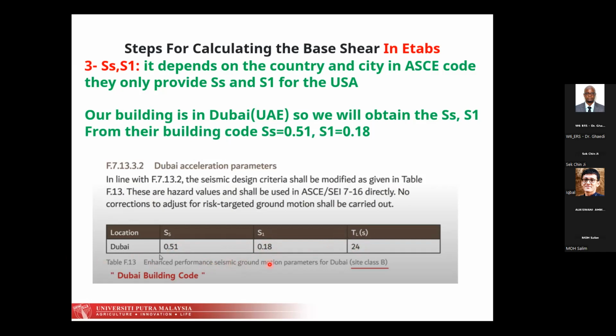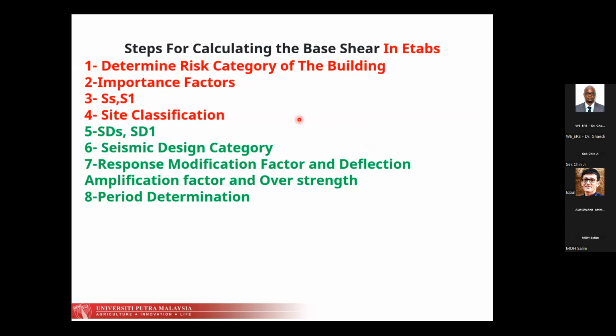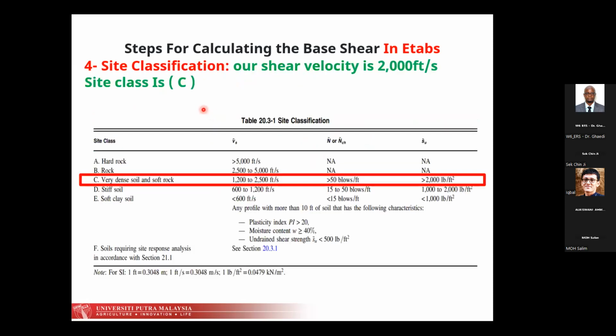And we should notice what site class is given. Because sometimes when we do a seismic hazard analysis for the location of the structure, it may be given for our site class, so we go directly to the design values. So we should notice which site class is given. This is given for site class B. So we should calculate SMS and SM1, and then SDS and SD1. But before we do that, we should know the site classification.